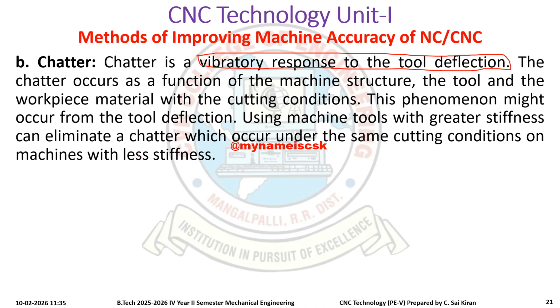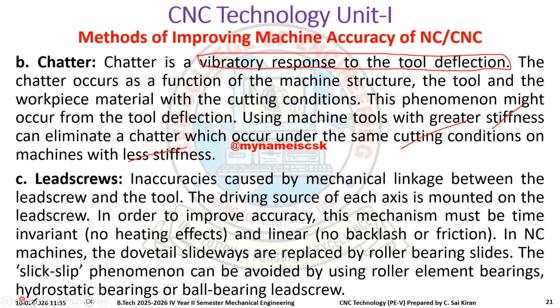This phenomenon might occur because of tool deflection. For the same improvement, we have to increase the stiffness and eliminate the chatter, which occurs under the same cutting condition again and again on machining with less stiffness. So we have to make sure that our stiffness is higher.